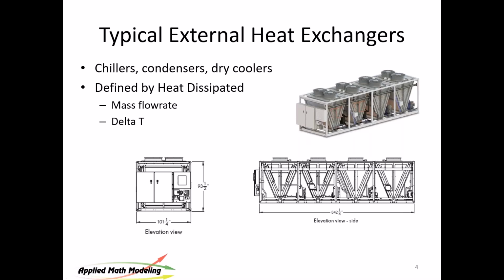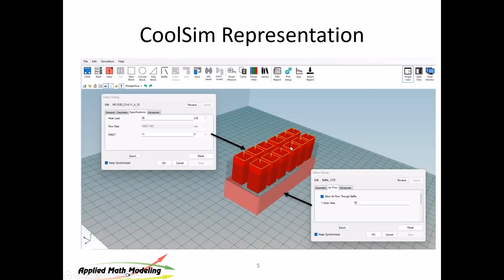In CFD, we fill the volume with elements. We tend to fill them in CoolSim with hexes. So we're hex dominant, and if we use hexes, which are rectilinear in nature, then using a rectilinear structure will keep our mesh count low and give us fairly good results. So that's how we do it, and it works quite well. So there's a basic structure. There are a number of these that you can build, and you can build them different ways. This is one way to do it.